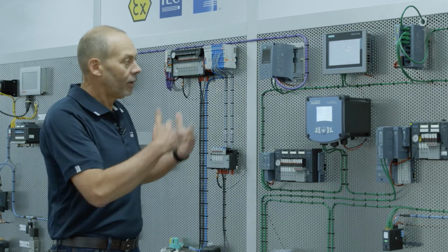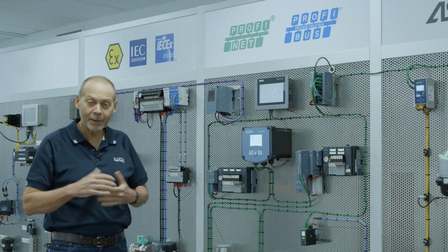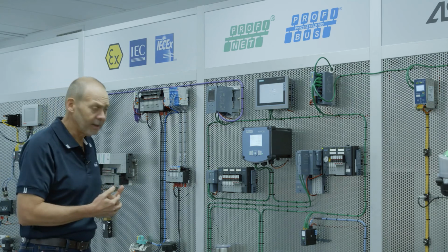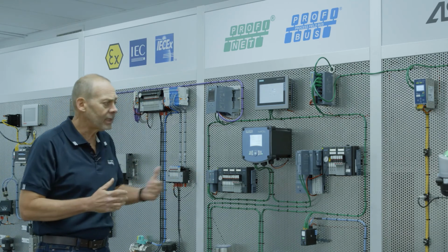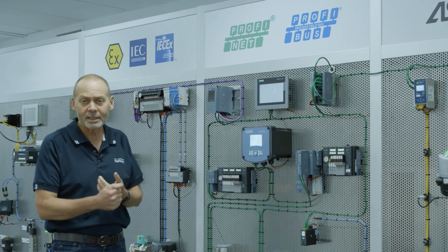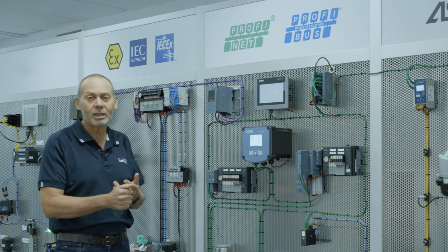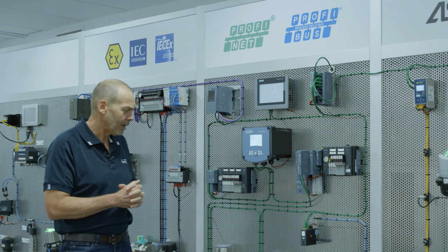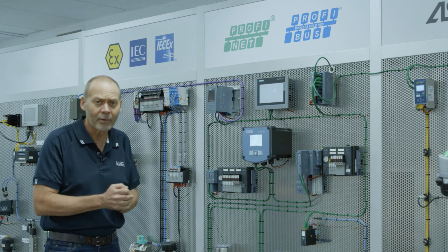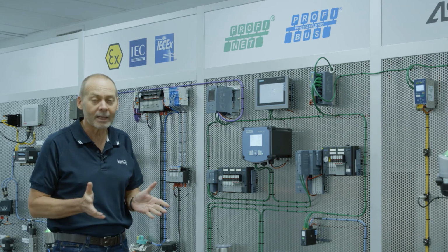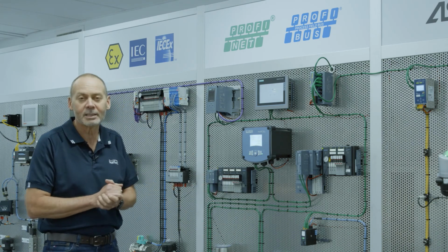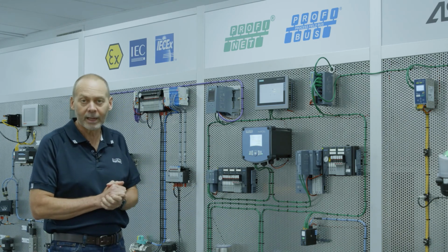That gives you an overview of most of the products we do on PROFINET. Applications where you would use PROFINET are anywhere where there's a large infrastructure or high level of automation. This could be a pharmaceutical plant where we have direct integration either in field devices or in I/O clusters. It could be in water treatment, desalination, food and beverage, or any of those applications. It's interesting that in food and beverage, water treatment and even pharmaceutical, around 30% of outputs are actually pneumatic. So this integration of pneumatics directly into the network, whether it be on the valve itself or in clusters, is quite valuable in automating those systems.